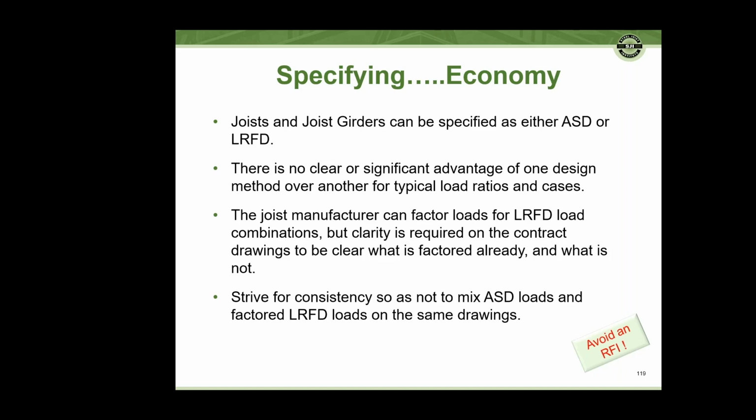Overall, we would ask that you strive for consistency so as not to mix ASD loads and factored LRFD loads in the same drawings. We're starting to see that pop up sometimes, where we're getting a combination of loads and lacking some clarity as to what's factored and what isn't.